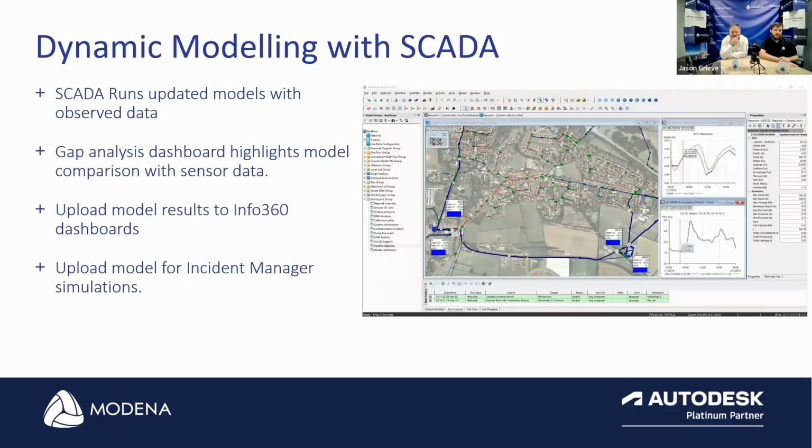Now, like we just said, this allows dynamic modeling with that live data. So we can even use this information and take the sensor data and publish that to a dashboard into elements like Info360 assets, where we can actually see what is happening to those live elements. So this is where the operators of the system would be able to see, all right, we've got a fluctuation in pump 13 happening at the moment. So we're expecting a drop over here anytime soon, or we need to do preemptive maintenance on this. So that's exactly where this software flourishes and actually stands out the most.